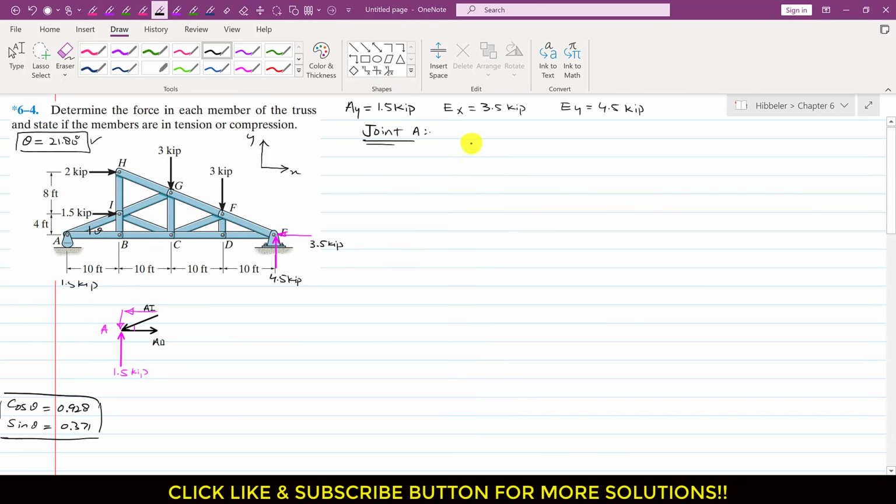If I apply the summation of forces along y equals 0 at joint A, we can see that this component is acting in the negative y direction and it is the sine component of AI. The sine value is 0.371, so I will write 0.371 AI, and this is acting in the positive y direction, so I will write minus 1.5, and this is equal to 0. So from this, AI equals 4.04 kips.